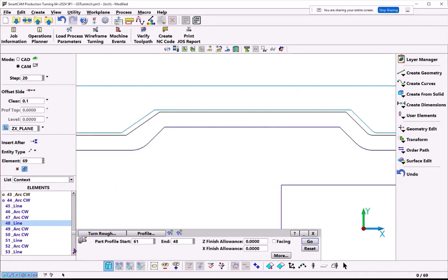There's a difference between hide and mask. Our stock and void layer are masked. That means they won't be used. You can't touch them. You can't do an element data. You can't do anything with them, except use them for verify. So my suggestion is don't ever use mask, except in things like this.